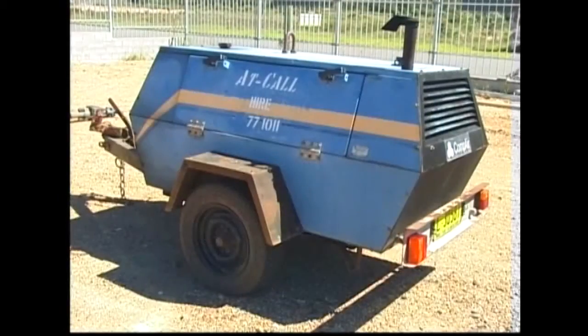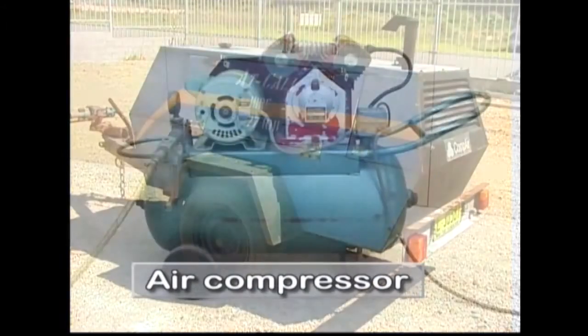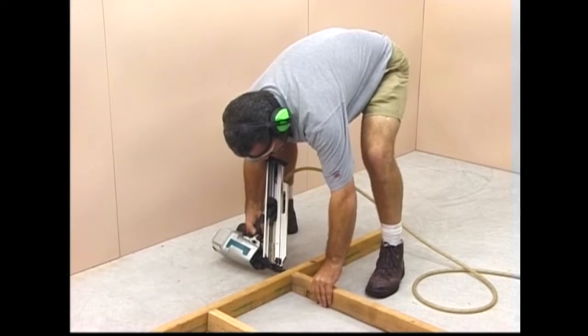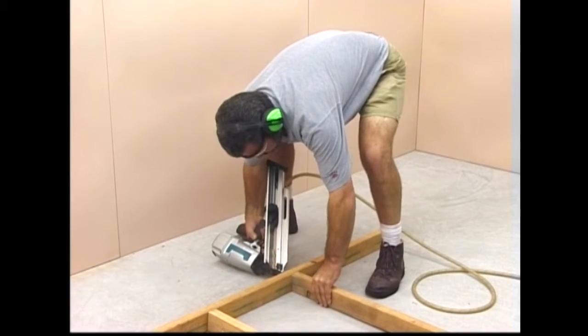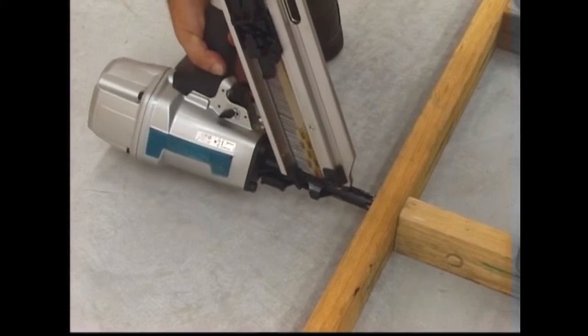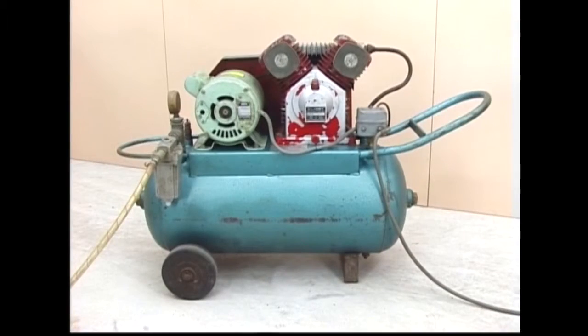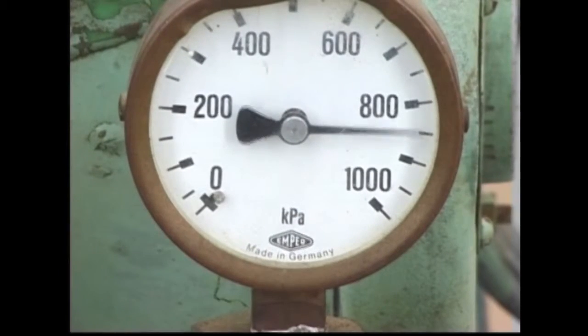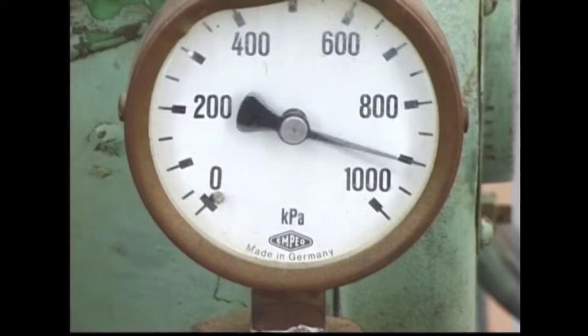As well as large trailer-mounted compressors, smaller electric compressors are used on job sites. They power nail guns and other small air tools. Compressed air is stored in a tank or receiver. A pressure regulating switch maintains constant pressure by turning the motor on or off according to demand.